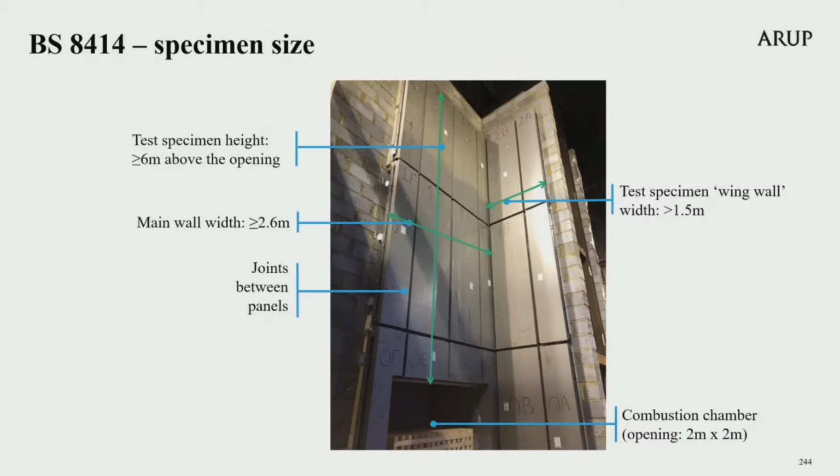British Standard 8414 states that the test specimen shall include all relevant components assembled and installed in accordance with the manufacturer's instructions, where cladding systems are defined as including sheeting rails, fixings, cavities, insulation and membranes, coatings, flashings or joints. This is provided at note 1 of the definition of external cladding systems.